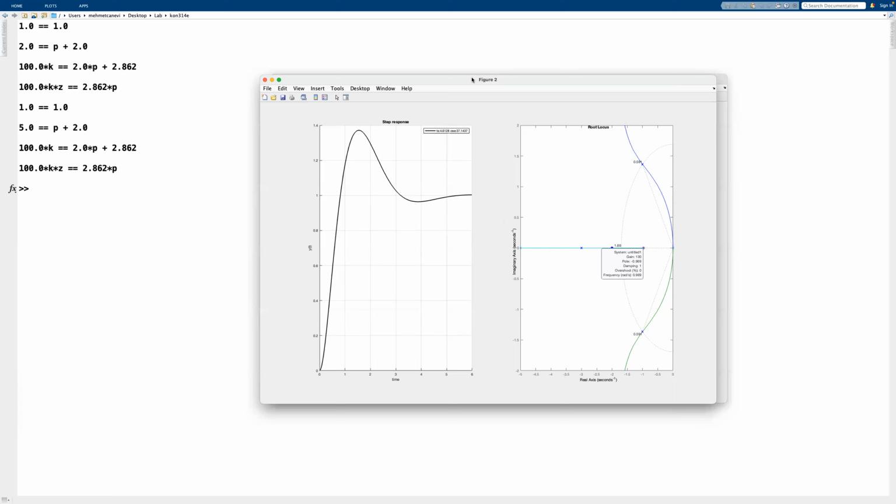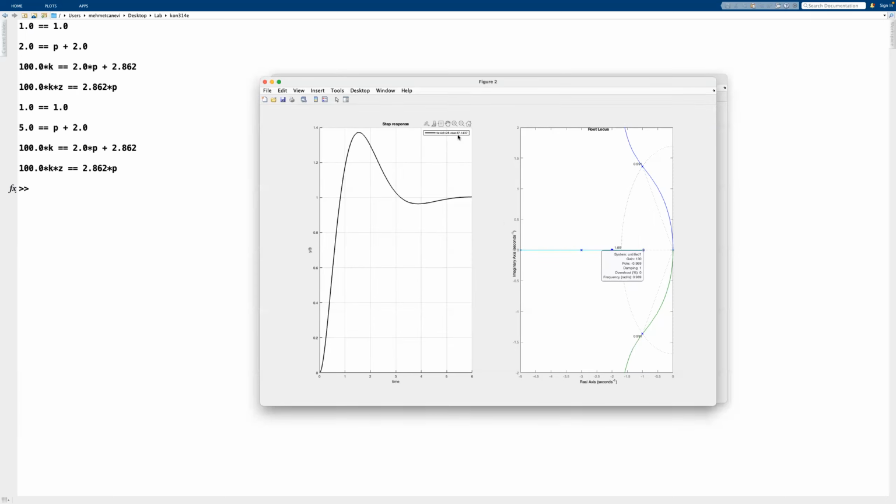And it reflects on the step response here. We can see that 37 point something percent is the overshoot, so we have a high overshoot. We were looking for 10%. Our settling time is not 4 but 4.6, but that's not because of our formula, because for this setup of poles and zeros the formula is not applicable, as it only concerns this pole pair. If you have another zero or pole, it doesn't reflect that system, so you cannot use the settling time formula.